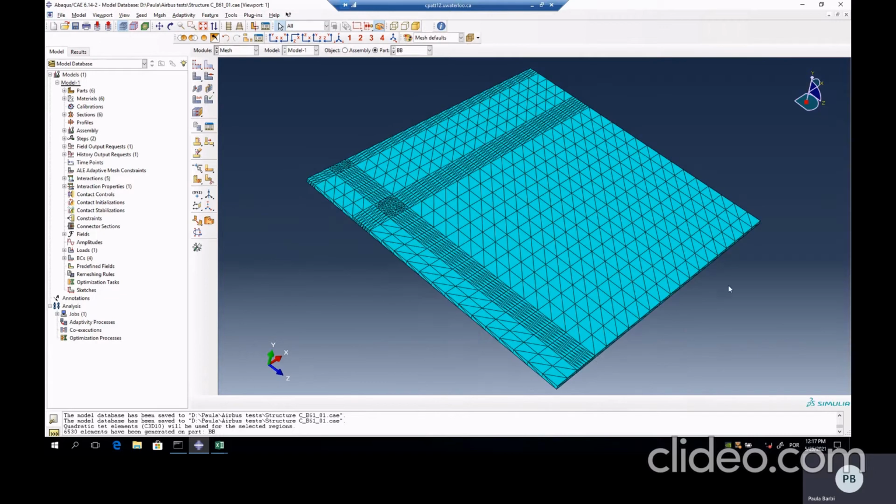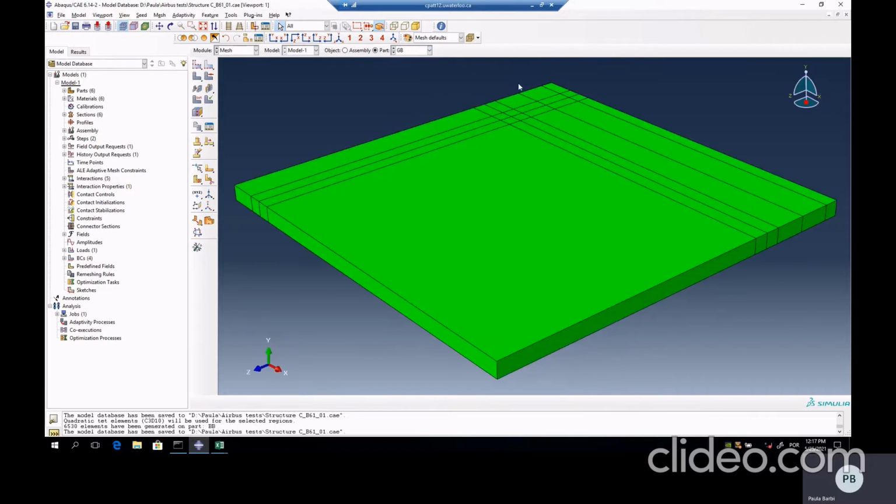One thing we could do here is to do the mesh a little finer next to the load and then make it coarser when it goes apart, but I'm not going to do this now. Okay, so now I gotta do this for all of the 6 layers that we have. I'll return the video when I'm done.